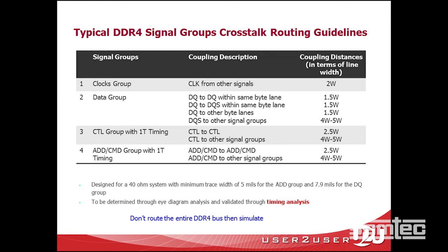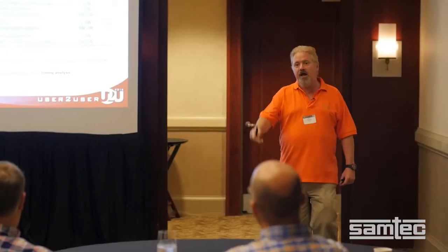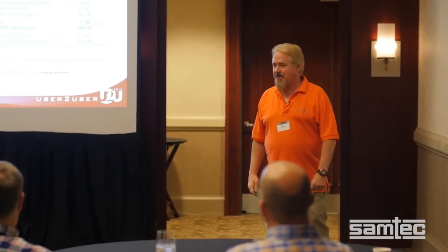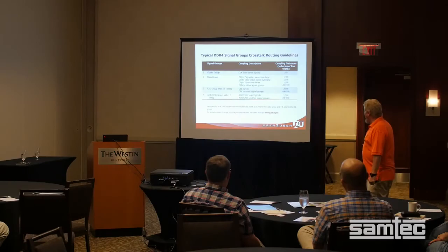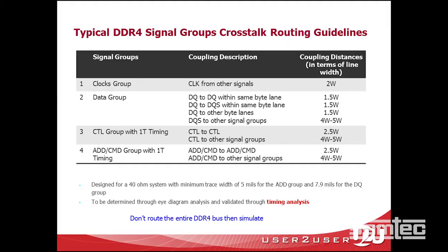Because remember, these depend on length if you're routing on the microstrip, the outside layers. Then how can they give you a spacing? They cannot. So you need to look at what kind of rules. These are the rules we got out of the controller.